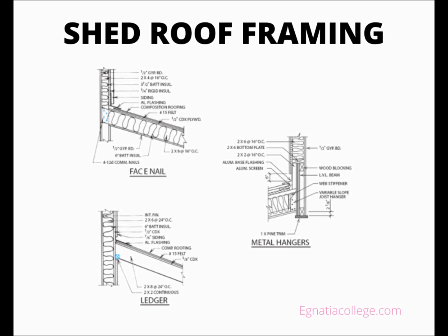Use 13 feet 9 inches, or 13.75 feet, as the run in calculating the length of common rafters. Where shed rafters butt against a wall or other vertical surface, the drawings should include a detail to show how they are fastened. The figure shows 3 methods of fastening rafters to a vertical surface.